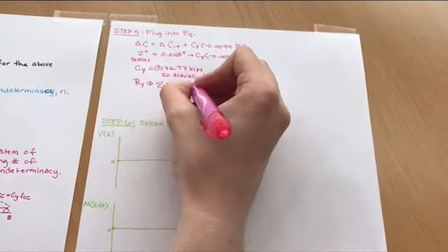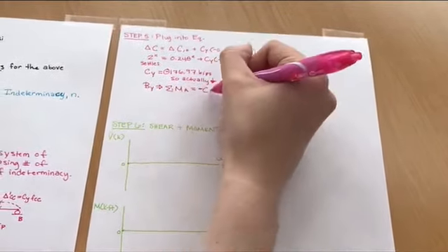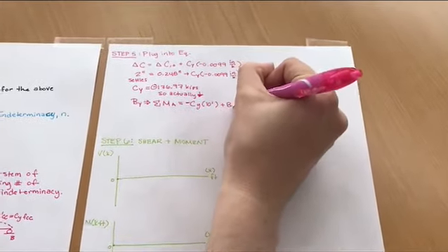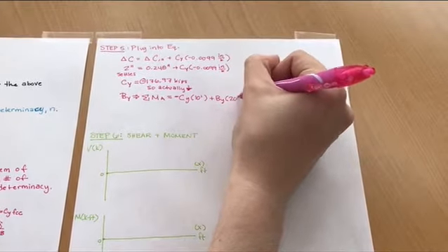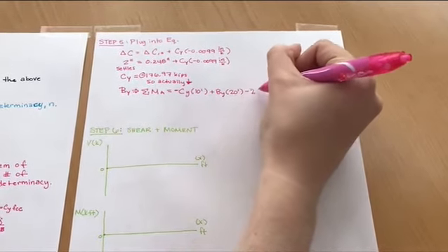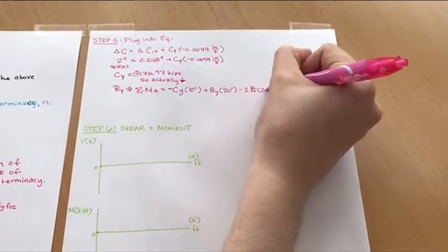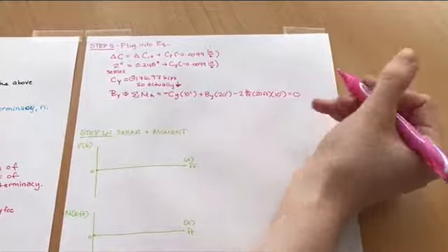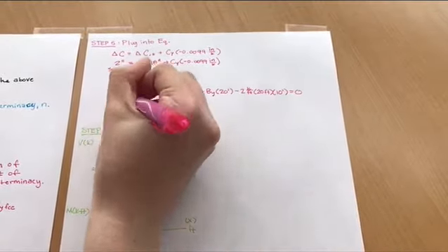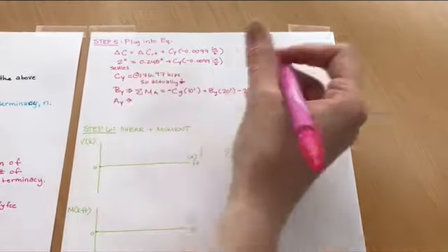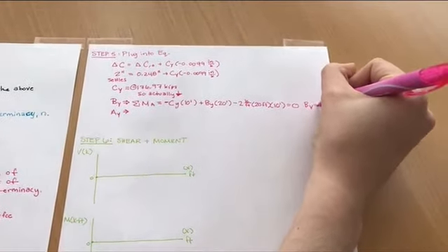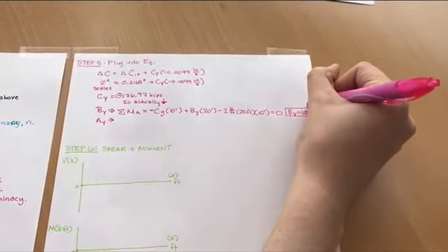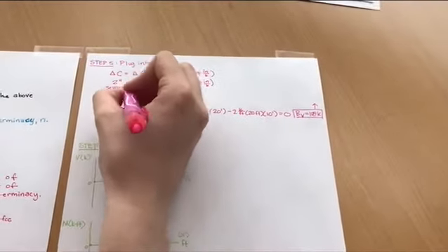As you can see, solving for CY, we get about 177 kips, but that's a negative number, and since we assumed it upwards, it actually acts downwards due to the settlement initially. Solving for BY, taking the moments about A, we assume that since CY is downward, assuming counterclockwise as positive, that will be negative. BY times 20 will be counterclockwise, and then the distributed load will be downward, making a clockwise moment. This gives you BY equal to 108 kips.